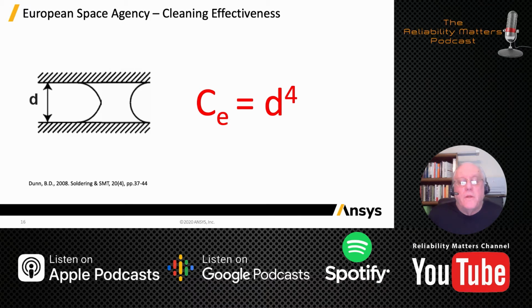And what he and his team had done, when he was at the European Space Agency, they were trying to quantify cleaning effectiveness. So we all know when it comes to cleaning boards that it's easier to clean under components where you have a lot of spacing. But what absolutely stunned me was that what they had shown was that the cleaning effectiveness goes up as a function of the fourth power of the spacing.